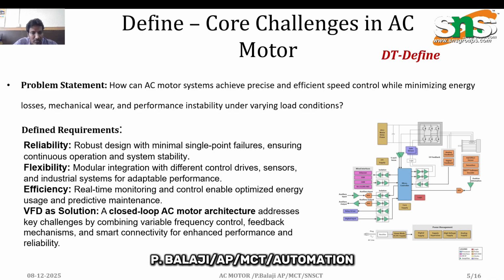To solve those problems, we have some key requirements: reliability, to ensure stable continuous operation; flexibility, allowing integration with different control devices and sensors; and efficiency, optimizing energy and enabling predictive maintenance systems. The solution is a VFD-based closed loop control system, which combines variable frequency control with feedback and smart monitoring systems.